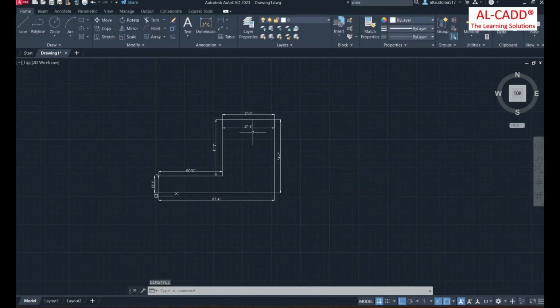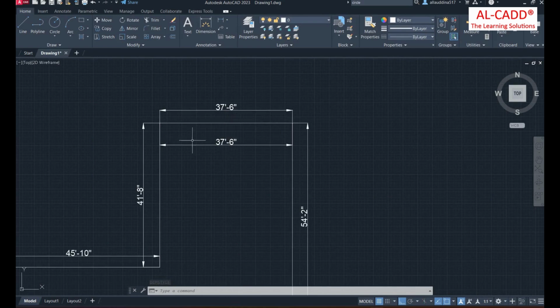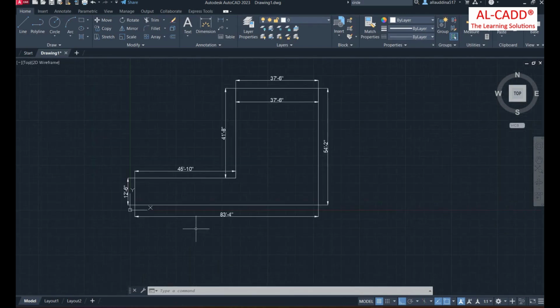And one more thing: whatever value we have taken in decimal, the 450 and the 1000, the correct value will not show in feet and inches in AutoCAD. Because we can't convert in AutoCAD, whatever unit you are using, we have to keep the project in that unit only. If you want to use feet and inches, you have to use a separate file. We can't do this in AutoCAD. In other software like 3ds Max, Revit Architecture and SketchUp, you can convert easily.